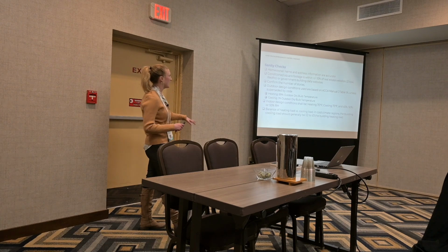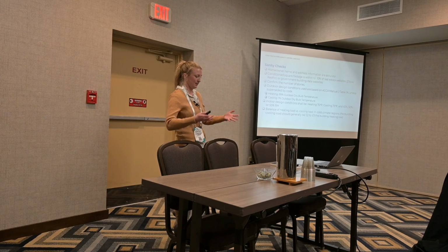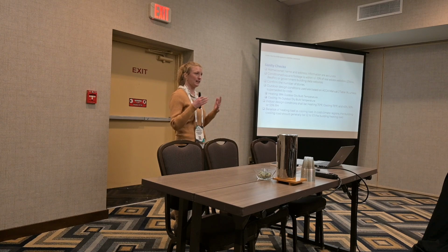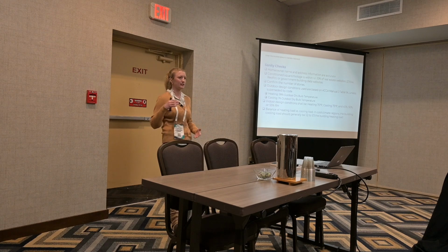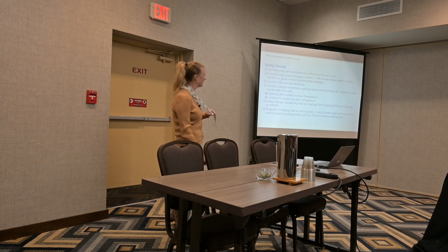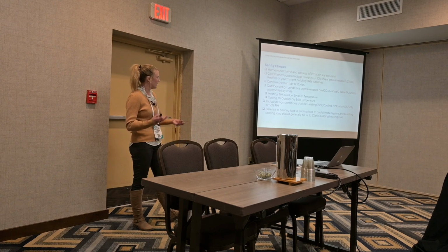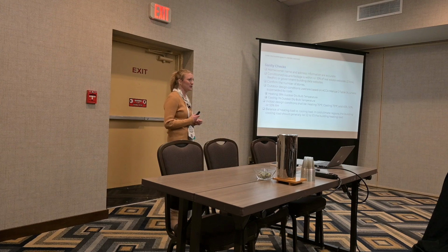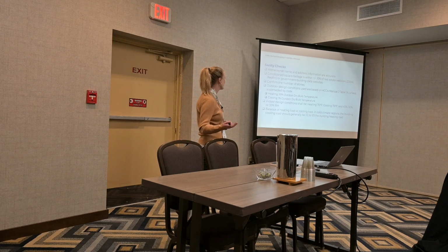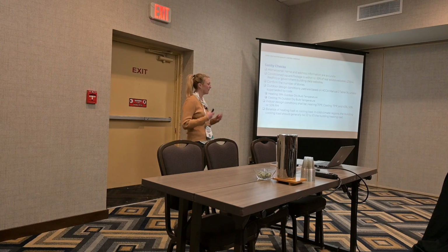All right, so these are just some sanity checks. Look at these as if you're cross-checking your coworker's load calc, and you haven't done much with the home, you don't know much about the home, you're just doing some quick sanity checks, and these are going to lead to some additional conversations with that person. So check homeowner name and address information are accurate. If you don't know anything about this home or the square footage, maybe a quick check would be, okay, is this square footage within plus or minus 10% of real estate websites? If it's not, then you'd have that additional conversation.